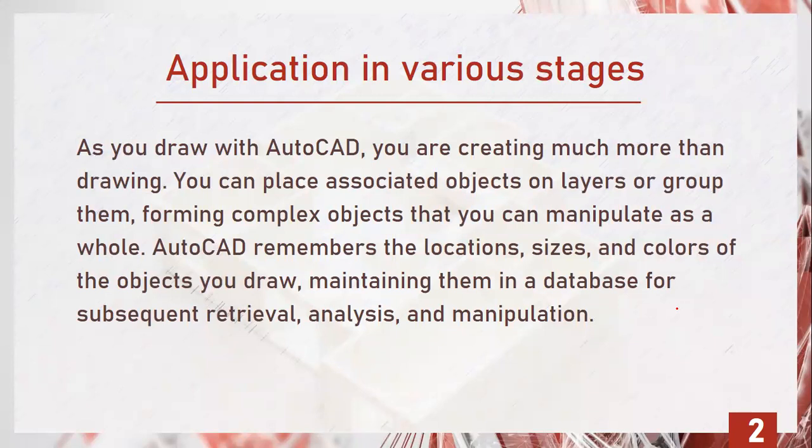Once we complete the drawing in AutoCAD, we can export that drawing into other softwares. Like what I do is I export the drawing into STAAD software or SAP software, and it plots the same drawing in that software, and I can take forward the drawing and analyze the building or structure in STAAD or SAP softwares.